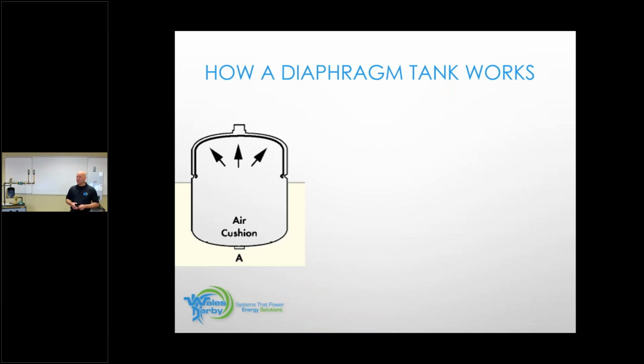And here we are. We're going to show you basically when you purchase an expansion tank, here we happen to have a cutaway. This is FlexCon. We're the FlexCon guys. So I purchased this. I take it out of the box. It should have 12 psi of air on the bottom side of this unit. What that does is when it's not tied to the system, it has the rubber diaphragm pressed right up against the metal. So we have a feed valve here, take-off feed valve, backflow preventer, set at 12 psi.